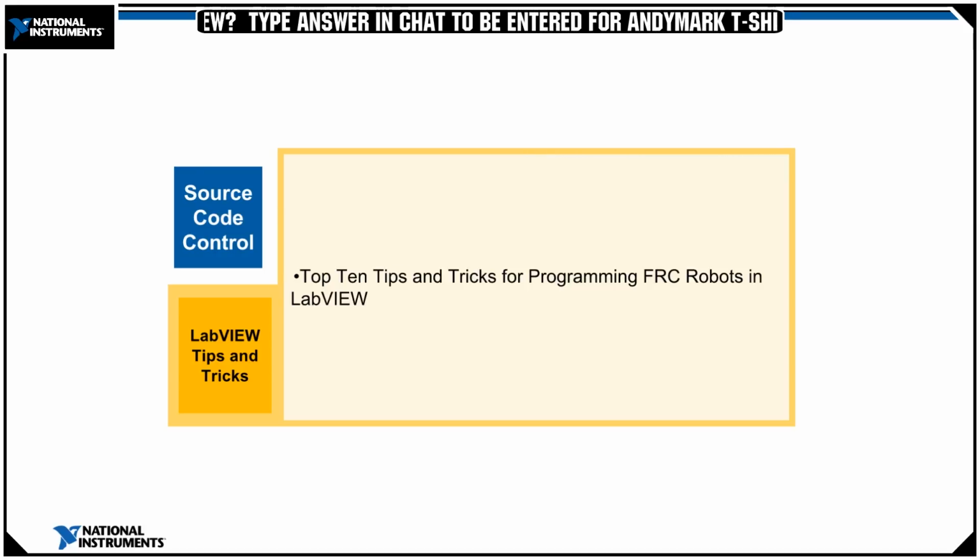All right, and the other question that we had was from Desolate10 asking, what is the best way to merge conflicts? The best way to merge conflicts is very carefully. It's a little difficult to go through LabVIEW and tell what's different between VIs. If you do Google for this, it is on ni.com as well. There is a program to diff LabVIEW VIs to go through and point out all the differences. It's not perfect, but to really resolve those conflicts, the best way is to just go through the two VIs manually, figure out what's different, and determine what changes you want to keep.